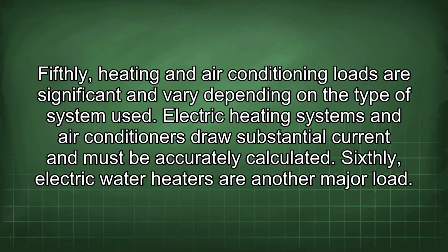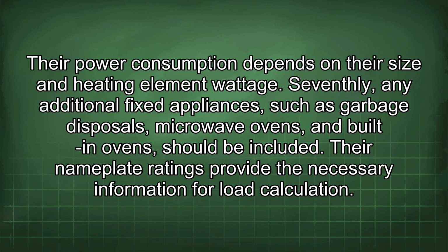Sixthly, electric water heaters are another major load. Their power consumption depends on their size and heating element wattage. Seventhly, any additional fixed appliances such as garbage disposals, microwave ovens, and built-in ovens should be included. Their nameplate ratings provide the necessary information for load calculation.